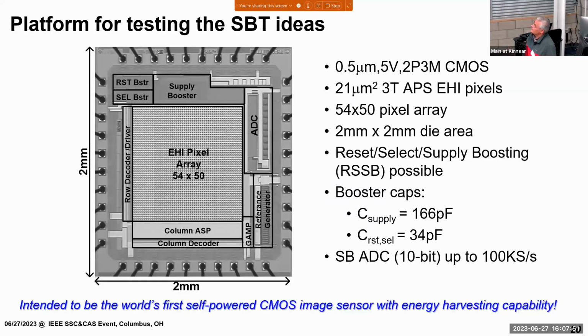And obviously, we put all those in, and also we developed a readout technique for image sensors using a boosted supply, boosted reset, and boosted select, which might be another talk. Or if you have time, I have the slides I can show you and take some time to explain that. But we put it in there.